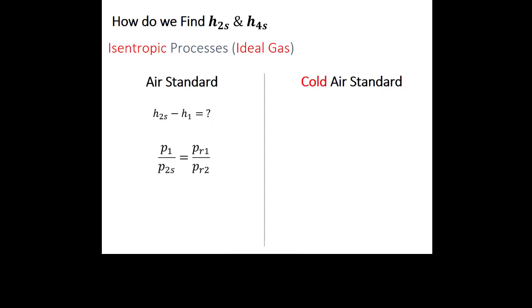And when I find my isentropic processes, instead of using an expression with k in the exponent, like we did for the last example, instead I use a pressure ratio being equal to the ratio of these Pr values that I find on table A22. Because they're open systems, normally I'll know pressure ratios and not specific volume ratios. Right? Often the thing that I'll be looking for here is Pr2, so I can fix then state 2 from table A22.